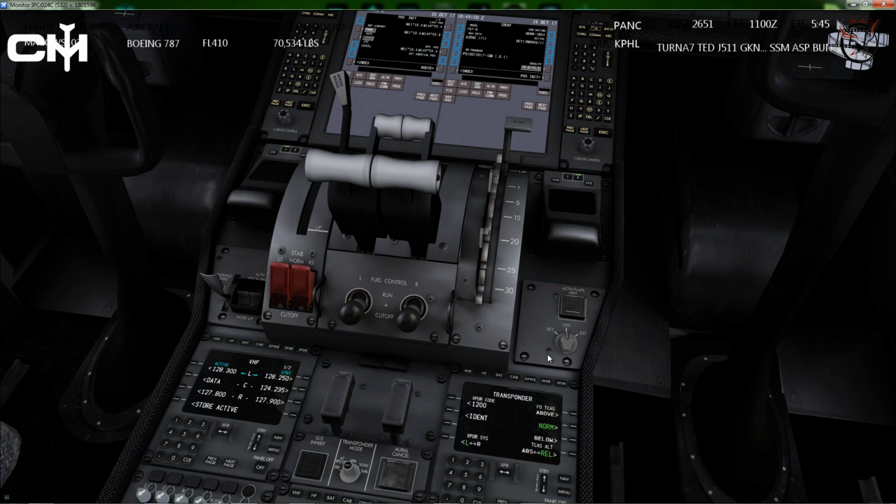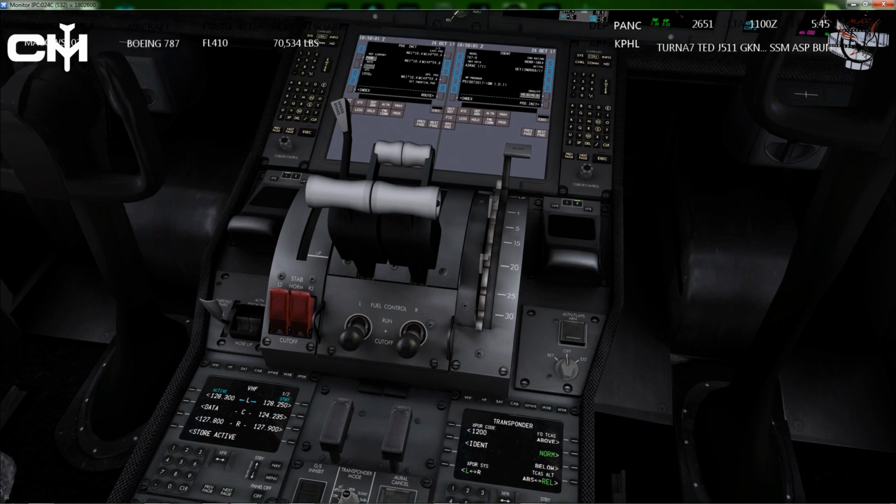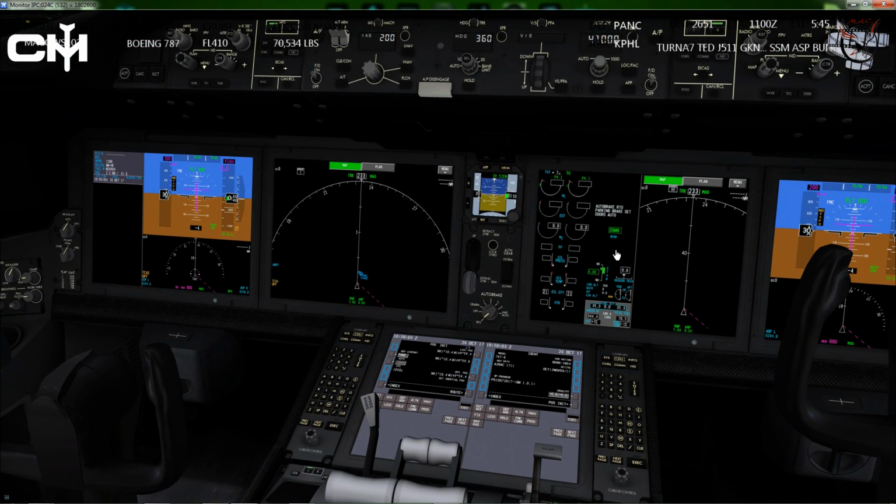Alternate flaps panel. These two need to be as we checked, or as we made sure they were set earlier. So guard closed, light off, and then off. So we're good on that. And it didn't say anything about the flaps. Oh, the flap lever is way down here. It says flap lever set, but if it's up, it shouldn't show anything up here. And then if you were to move the flap lever even one setting, it would show that on here even though the flaps wouldn't move. So I just bypass it.